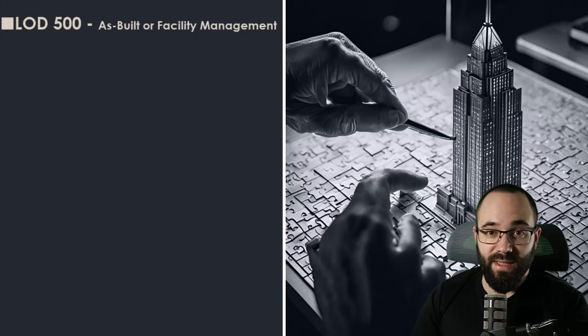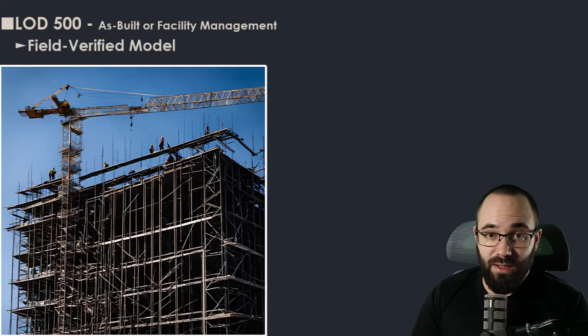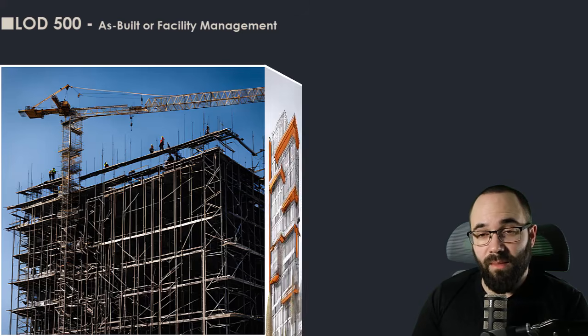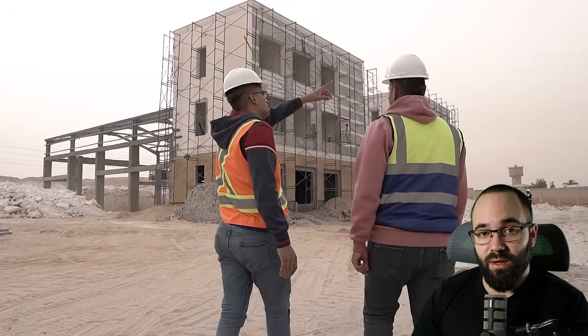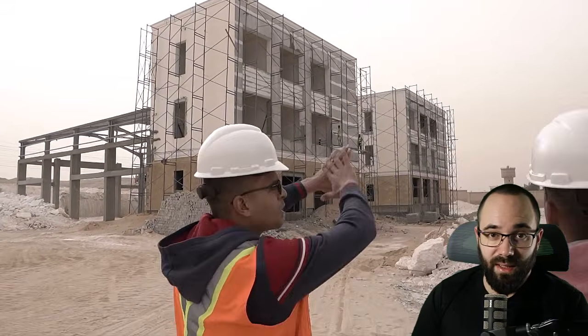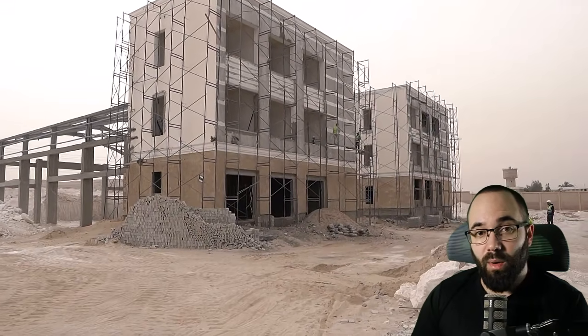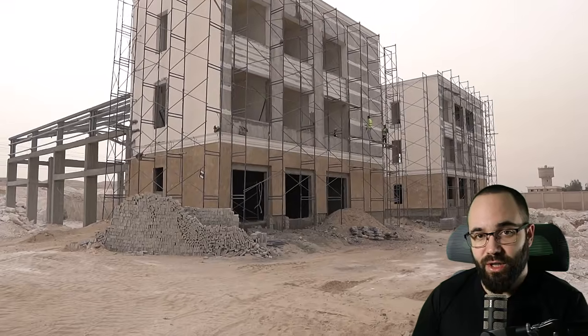So this includes a field verified model. At LOD 500, the BIM model mirrors the constructed reality. It provides a comprehensive representation of all of the elements within the building, reflecting real-world conditions after construction.